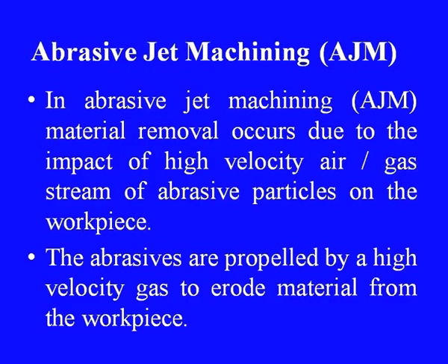In abrasive jet machining, material removal occurs due to the impact of high velocity air or gas stream of abrasive particles on the workpiece. The abrasives are propelled by a high velocity gas to erode material from the workpiece.